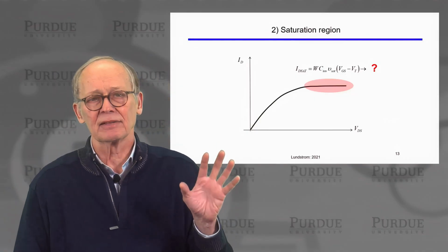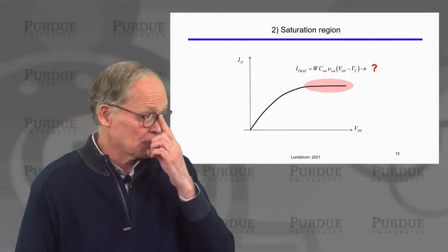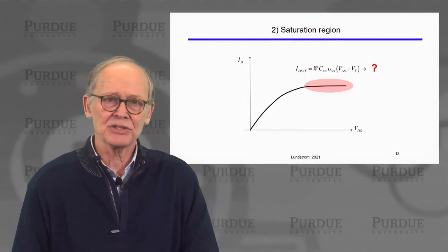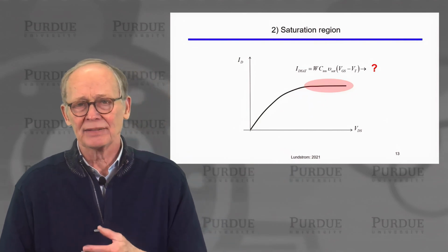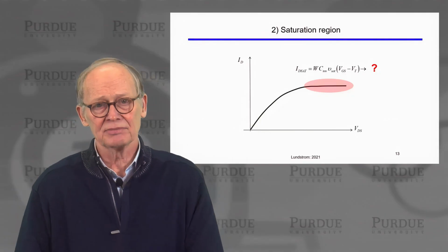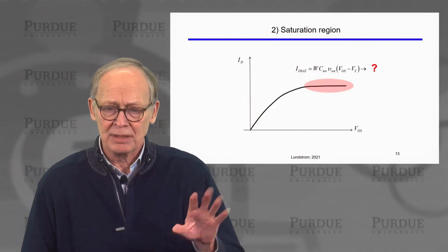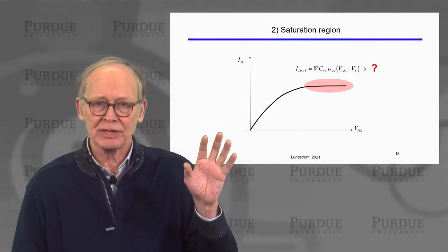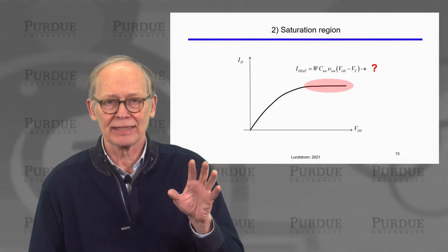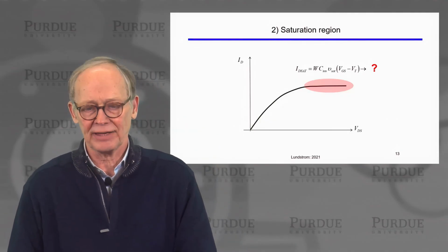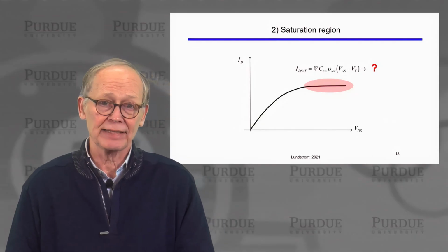Okay, we have discussed the linear region current. Let's discuss the saturation region current. We have a simple velocity saturation expression in which Vsat, which is about 10 to the 7th centimeters per second in silicon, higher in other semiconductors, III-V semiconductors, for example. But the traditional velocity saturation expression assumes that the velocity saturates because of strong scattering, and it just gets harder to push the electrons any faster. What happens in this ballistic device for which there is no scattering in the device?